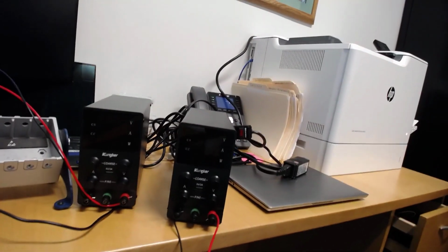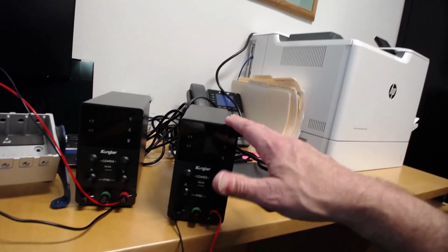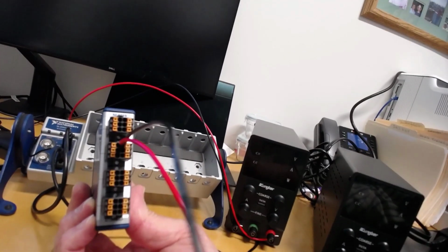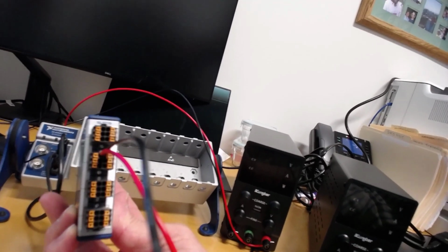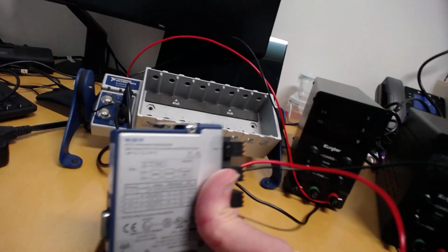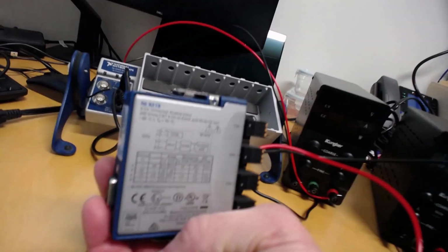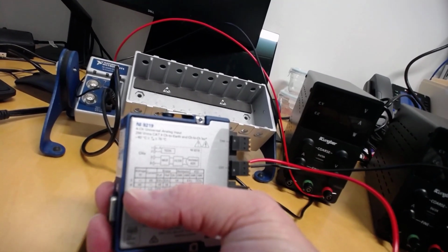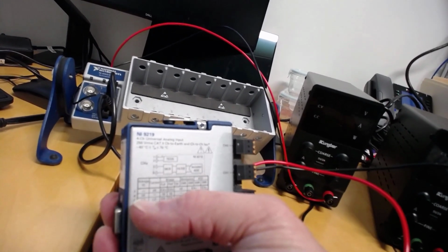I have two power supplies. You see this one right here, this one right here. And I'm using the module that you guys use in lab, the 9219. If you Google this module, you'll get the manual from NI that shows the wiring. Also, most of the modules tell you on the side. You probably can't read this, but it says voltage number 4 and number 5. So 4 is high or positive and 5 is low. That's where I'm going to plug things in.